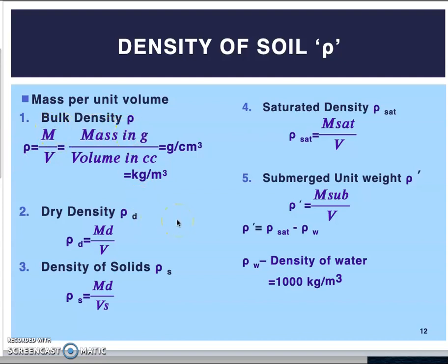If you go to the plot and you want to find out what is the density of the soil that is available in your plot, what you will do, you will take a sample of that soil. Maybe you will take a core and hammer that core. A core is nothing but, you can imagine, a small hollow section, a small cut section of a pipe. The diameter is usually around 10 centimeters, and the height of that pipe will be around 13 centimeters. So visualize something like this.